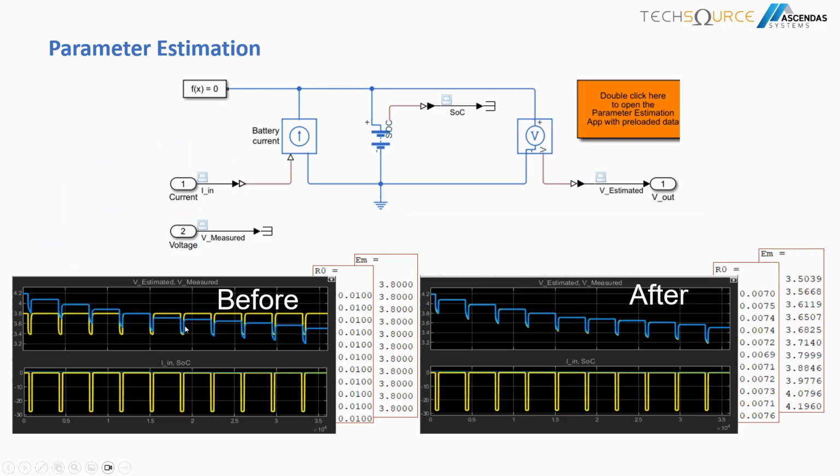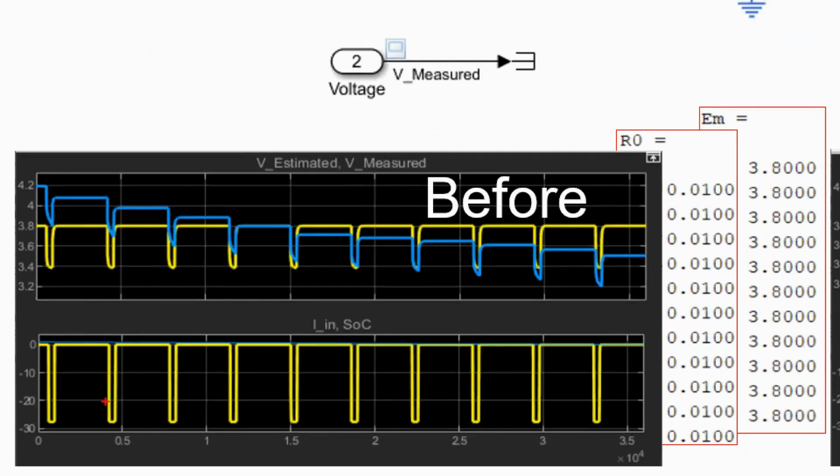So in this case, for example, we have a data. The blue data that you see here is the actual data of the battery. This is almost like HPPC data, but more on the discharge voltage in this case. So this blue line is the actual battery cell measurement. The yellow one is the parameters that we use for the model of the cell within Simulink or maybe the tool.